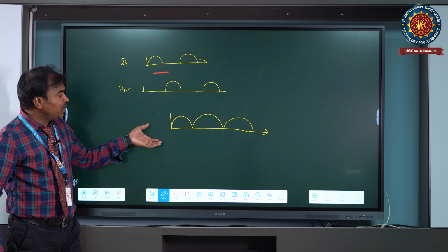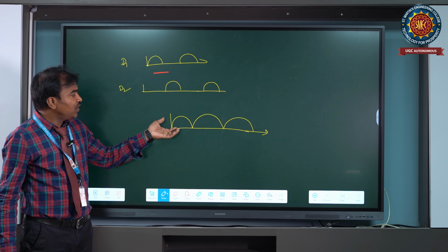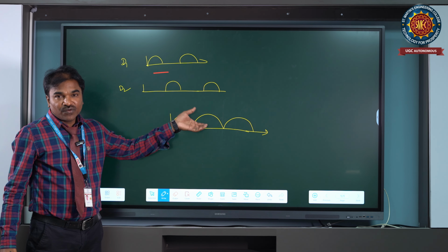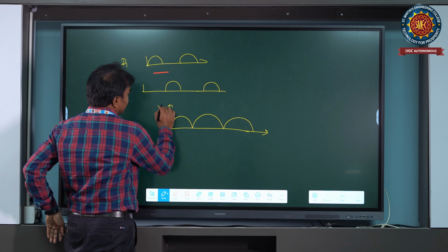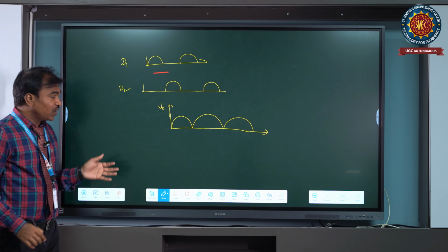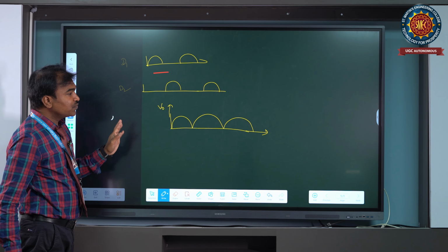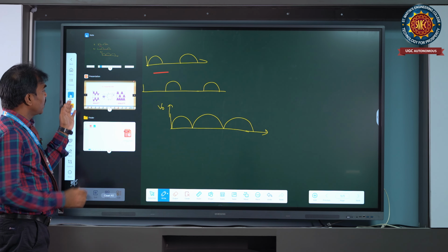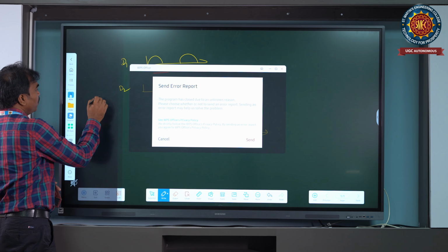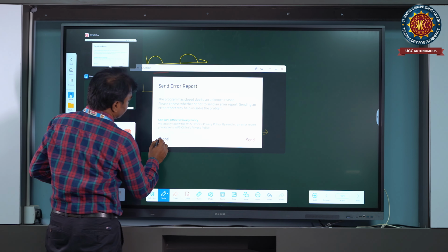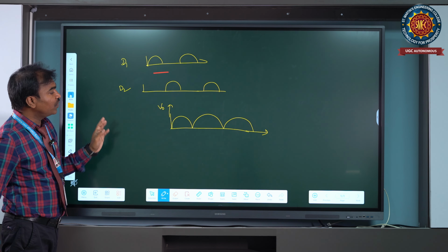Why this type of output? Because we are using two diodes, and one diode is on at a time. When we apply the negative going pulse, the other diode will be on. So this is the output of this one, and this is the full wave rectifier output.